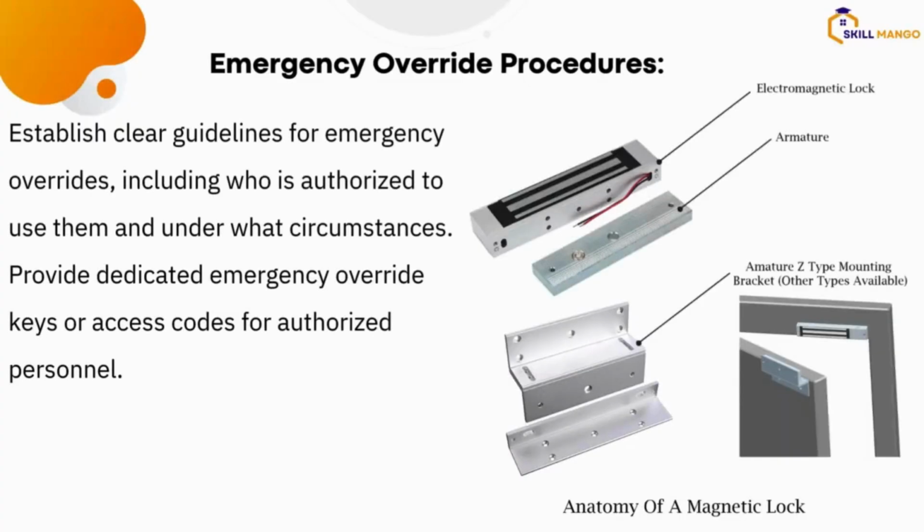And let's look at emergency override and procedures. Let's assume there is a fire outbreak. These are the issues that you have to understand as a new system integrator just coming into the market. You have to understand how this works because in case of a fire problem, they will ask you how you disengage the system. You have to plan and provide a strategy for your clients in case of a failure, when people have to troop out.